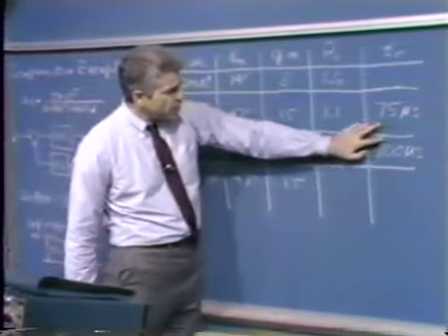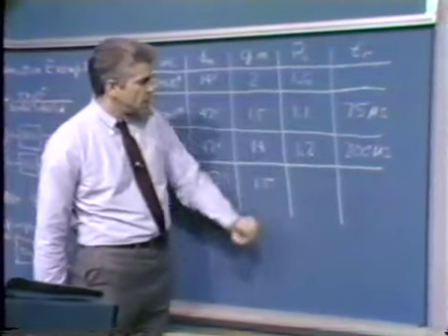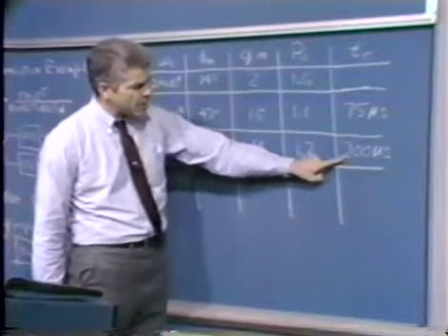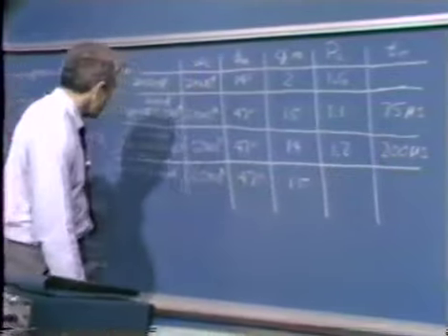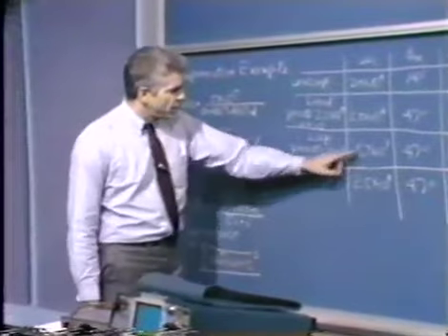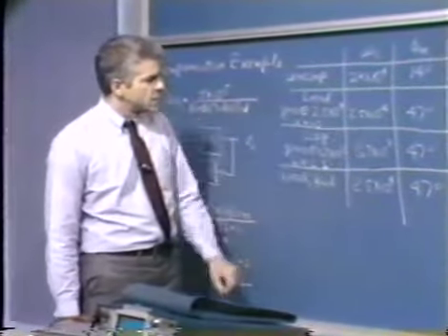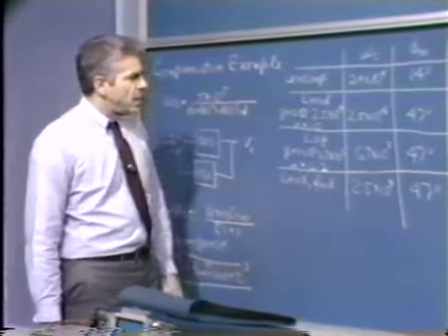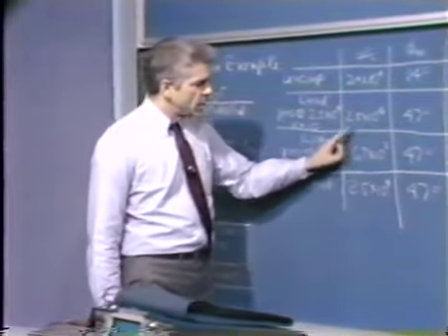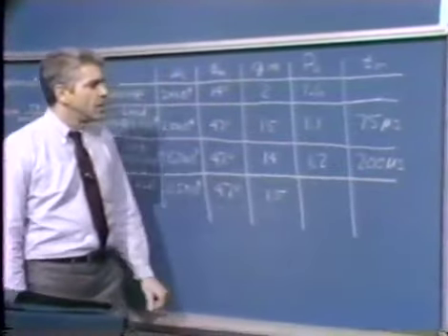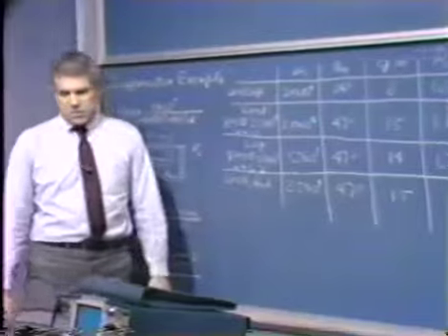Furthermore, there's roughly a 3-to-1 difference in speed of response, the lag compensated system being a factor of about 3 slower, whereas there's roughly a 4-to-1 ratio in crossover frequencies. And so that's a little bit bothersome. Here there's very nearly 4-to-1 ratio in crossover frequencies, actually a little less than a 3-to-1 ratio in speed of response. That's a little bit disturbing.